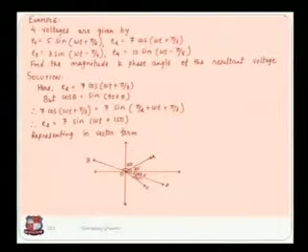As we know, the instantaneous induced EMF or instantaneous induced voltage equation is in the form of sine only, but here it is given in the form of cos. So first of all you have to convert it into the form of sine and then draw the vector representation. So here E2 is given as 7 cos(omega t plus pi by 3).